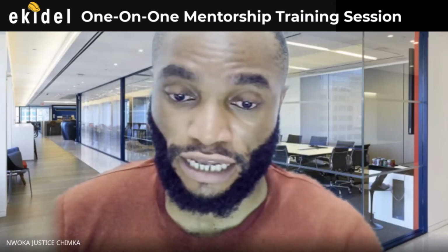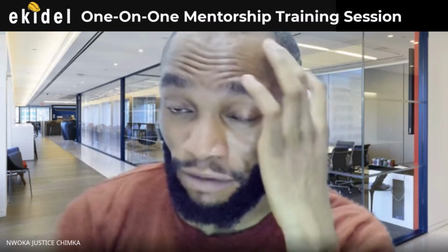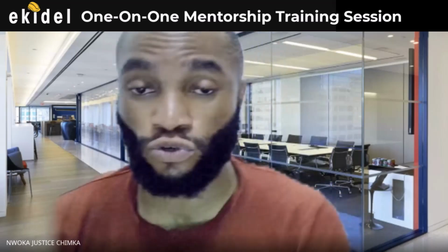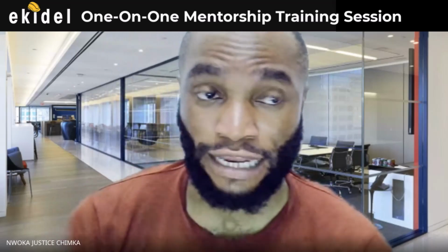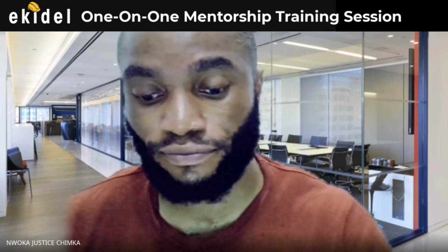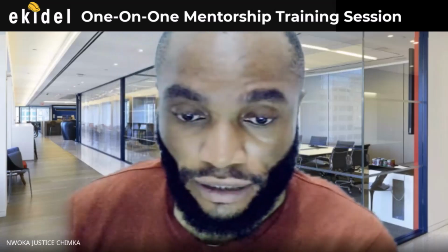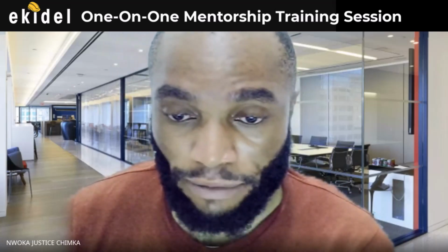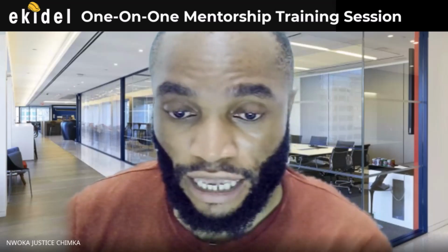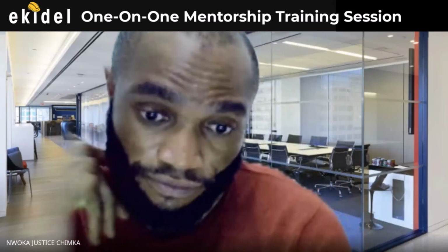This is just the distance between the face of the pile and the face of the pile cap. If it is too close, it will crack the pile cap at the edge. Exactly. So we can say okay, 150 and then 150. Then this is the pile cap depth, which has a formula actually. But let me hear, what do you say?